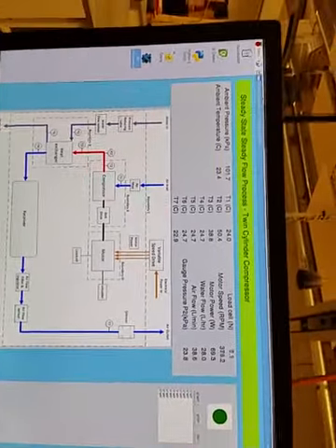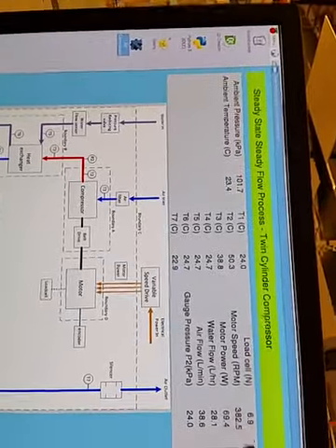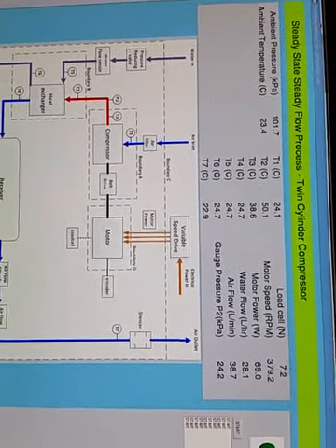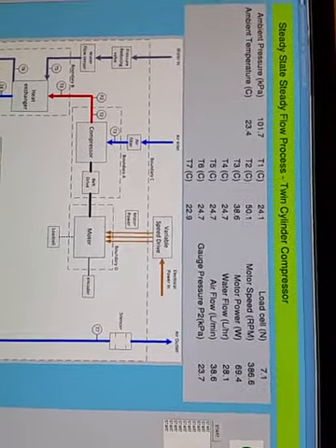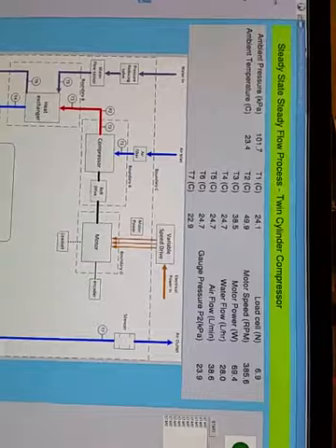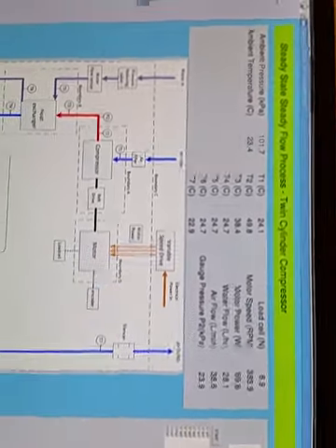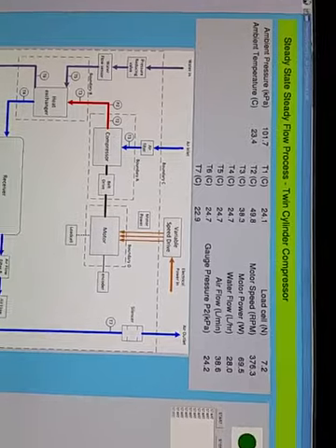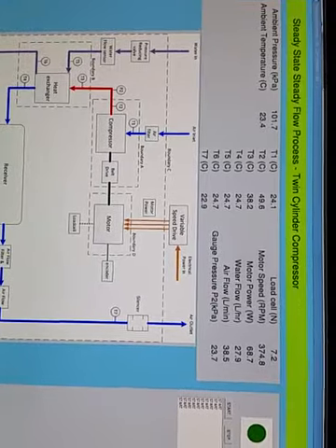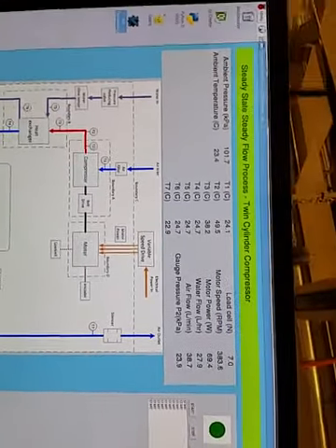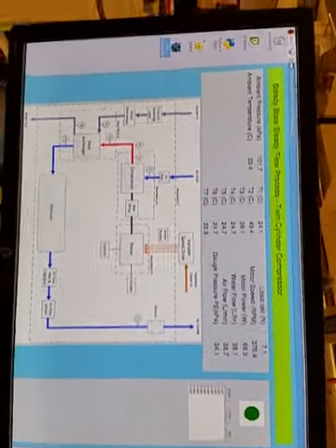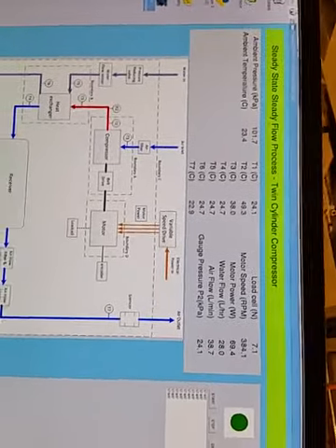Technically, for different motor speeds, you would have different values. During the lab, normally we take recordings of 3 sets of data, where we take the recording at this time here, and then we wait 5 minutes and take another measurement, and then a third measurement after another 5 minutes, and we take the average to use in our lab report calculations. So that's in terms of this screen here.